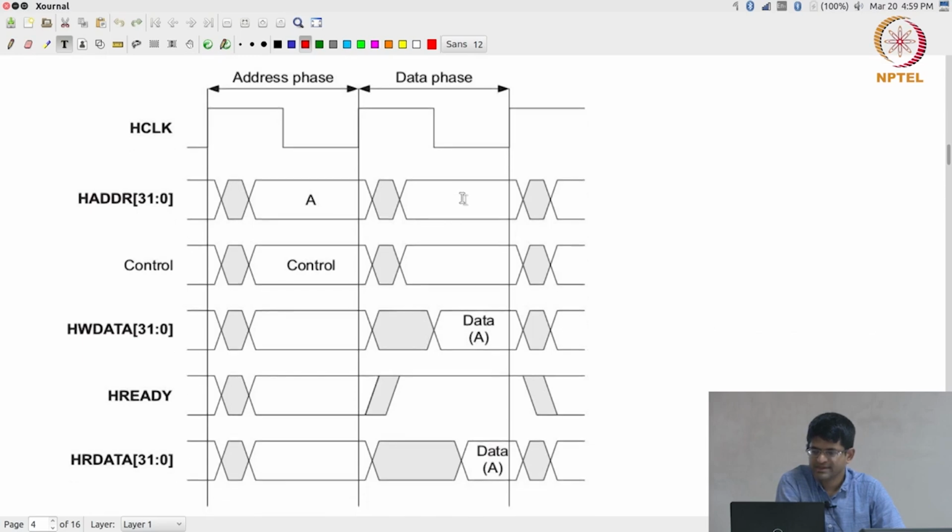So, now let us start looking at what a bus transaction looks like. And as far as the bus transaction is concerned, we need to essentially look at a lot of these timing diagrams. These timing diagrams are going to be common throughout the rest of this presentation. You can figure out what is going on over here. Essentially, you have a clock signal right on top, and the clock signal is just a square wave, as you can see over here.